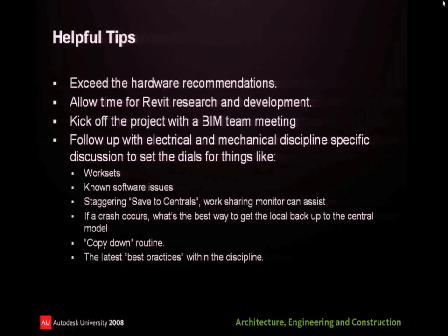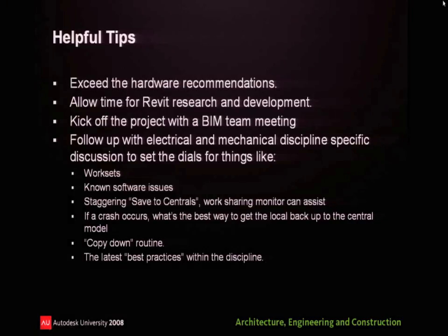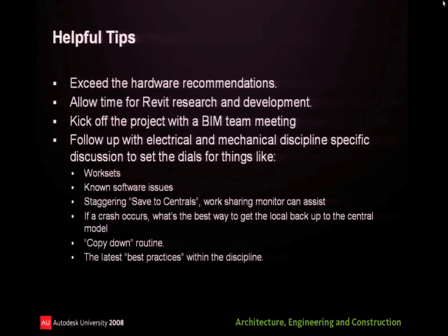What it was is people were talking about trying to do a transparent local copy procedure so that they could give their users a better way to copy down the files. They don't have to copy it every morning, rename it, and then the next morning repeat the cycle. It also keeps you away from having stale models out there. A lot of times you can have a stale model. Somebody hasn't worked on a project for a week, and something has happened where the central model had to be reestablished. Their model is no longer linked to central once there's a new central established. If that happens, somebody could work all day in their model and go to save to central at the end of the day, and they are not going to be able to save that data out.